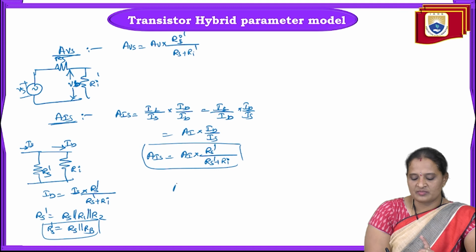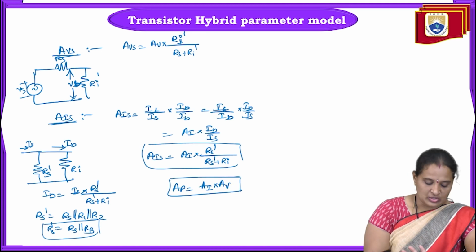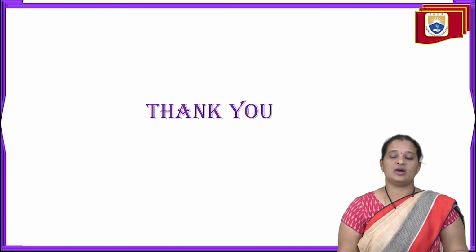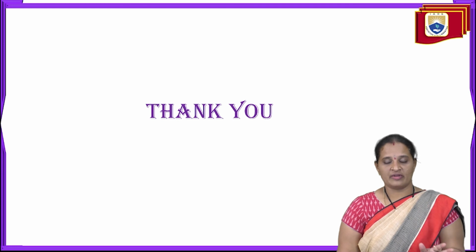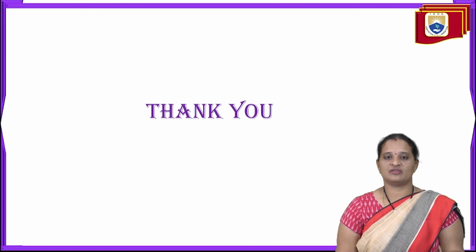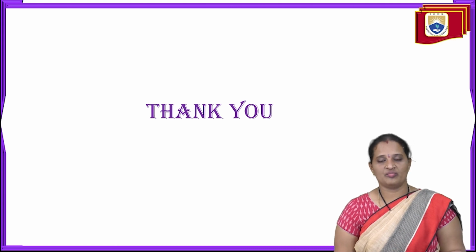So this is how we can calculate all the parameters. If in any problem we are asked to find the power gain, simply we can calculate it as the product of voltage gain and current gain. So this is the solution of all the problems on common emitter configuration. I hope you all are clear with this concept. So I hope you can solve any of the problems on common emitter configuration. The thing is, you need to remember the H parameter values and the basic formulas of the transistor circuit so that you can solve any kind of problems.